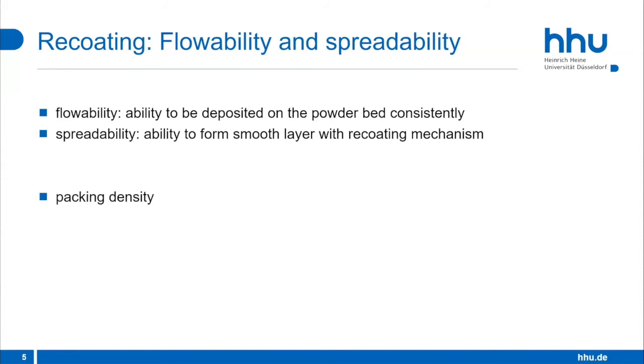Another issue with larger particles is that they automatically increase the layer height. So we can take particles with a diameter of 500 micrometers as an X50, but then you will have layer heights in a very similar range and your resolution drops and also your feature size is decreased.